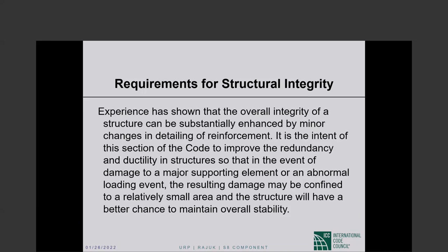You know the situation. If the top surface is exposed and the bottom surface you think is relatively more protected, you may want to place more of the reinforcement near the top surface and less near the bottom, or all near the top, but it is entirely up to you. The code doesn't restrict it.